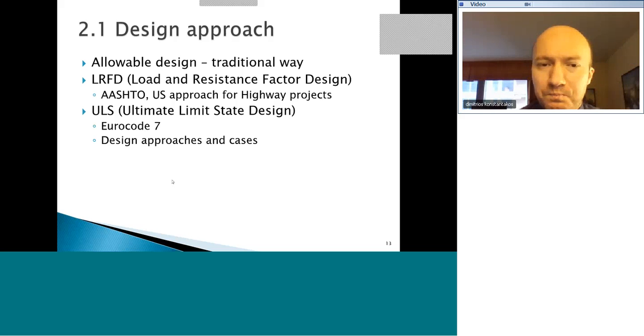It's really mandated mostly by DOTs, Departments of Transportation, for highway projects and railways. So they ask for it because all their projects have to be compliant with LRFD. But we'll see that there are some challenges. And in Europe and some other parts of the world, there's ultimate limit state design, what's called the ULS, which we're calling here Eurocode 7. The idea is that you apply partial factors to strengths, loads, and so on, and you create a series of combinations.